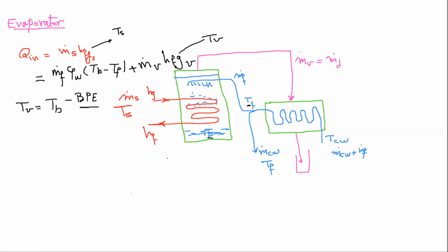Boiling point elevation, you can obtain this value either through a correlation. You'll find the correlation in the file that I uploaded today, or I'm going also to upload a book. The book is Fundamentals of Seawater or Saltwater Desalination by Hisham al-Dasuqi and Hisham al-Touni, and you'll find that in the second chapter of this book, he's talking about this kind of technology and has given it in details.